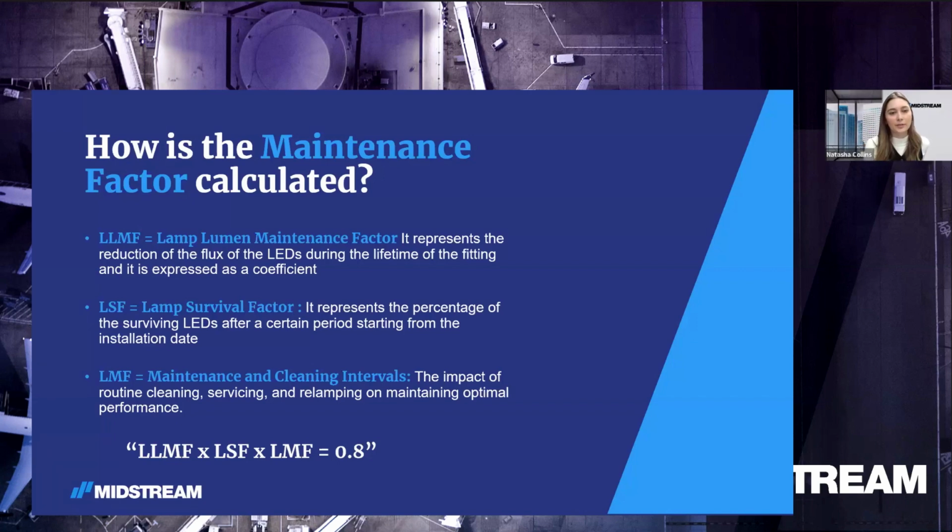Thanks, Paolo. I was actually just going to follow up with a question. Whose responsibility is it to calculate the maintenance factor? So the maintenance factor responsibility is for whoever's doing the lighting project, which does not mean whoever's doing the lighting calculation per se, the simulation, but whoever's setting the parameters for a lighting plan, which could be the operator of the airport in this case, or an engineering consultant working on the project, or it could also be the manufacturer itself doing the simulation if they have enough knowledge to do so.